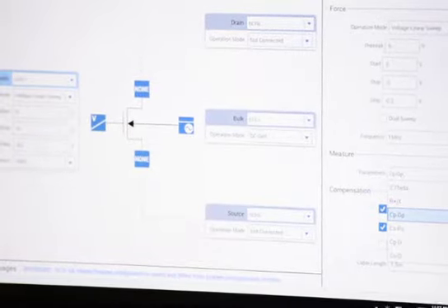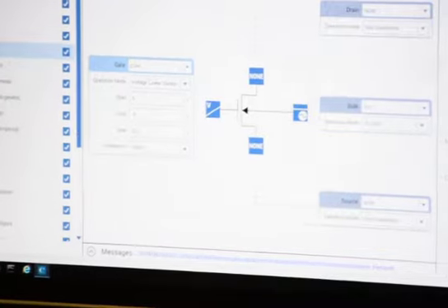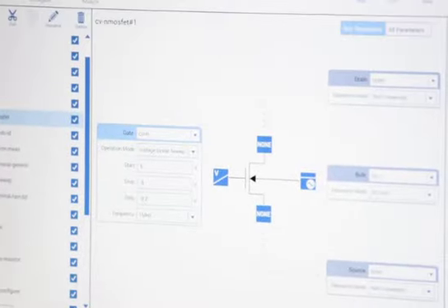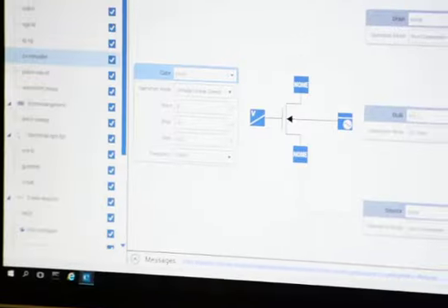There's a modification coming to the CV card that will allow us to measure smaller capacitances. We're changing the drive voltage. Right now it's plus minus 30 millivolts AC. We're increasing it to 1 volt. So we're going to have a 1 volt AC drive on a new modified CV card that will allow us to measure much smaller capacitances. So if you need that, let us know, and we can modify yours.